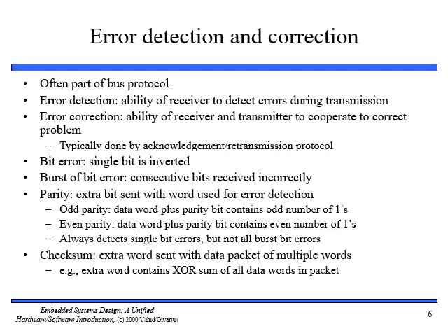So what we did, we computed the XOR sum of all data words in a packet and we send this along with the data packet. Upon receiving the data packet words and the checksum word, the receiver will compute the XOR sum of all the data words it received. If the computed checksum word is equal to the received checksum word, the data packet is assumed to be correct. Otherwise, it is assumed to be incorrect. Again, not all error combinations can be detected.